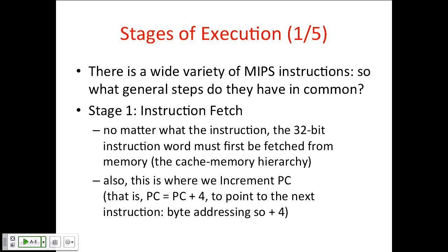So you can view the memory as a big combinational block that you send 32 bits and tell it you want to read those bits, and sometime later 32 bits come back that represent what was stored at that address in the memory at that point in time. And the processor captures that and then starts decoding those 32 bits of signal.